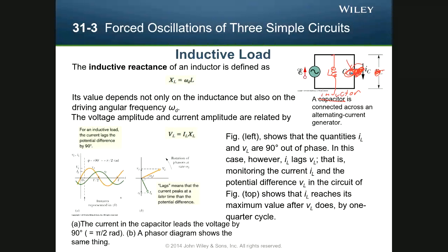So now when we look at an inductive load and a capacitive load, we'll be able to use something similar to Ohm's law, but not with capacitance and inductance directly. What we'll have is something called the reactance: a capacitive reactance and an inductive reactance. The inductive reactance is the product of the driven frequency, the frequency of this thing right here, times the inductance L of the circuit. So part of it is from the driver and part of it is from the circuit.